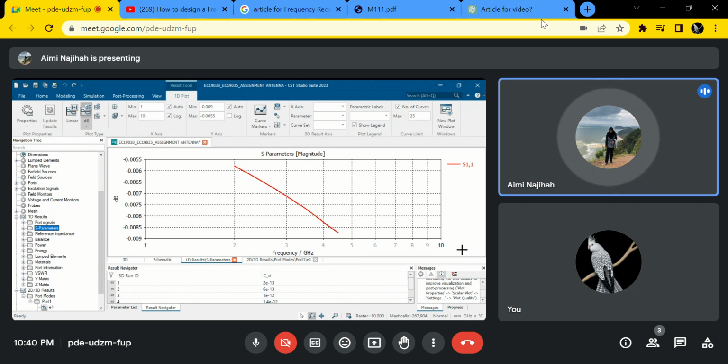The radiation pattern is a graphical description of the relative field strength transmitted from or received by the antenna. It defines the variation of the power radiated by an antenna as a function of the direction away from the antenna. The patterns are usually presented in polar form with dB strength.